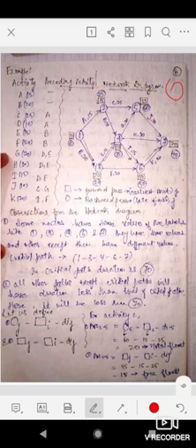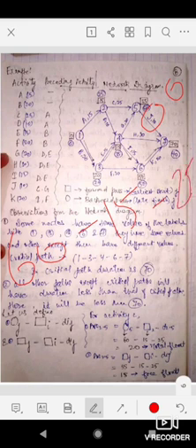So what can we do? For arc 2 to 5, latest finish time is 60. So we will take latest finish time minus earliest start time, that is 15. See here, 60 latest finish time minus earliest start time minus project duration, so we will get 20. This is the total float: latest finish time minus earliest start time minus project duration.